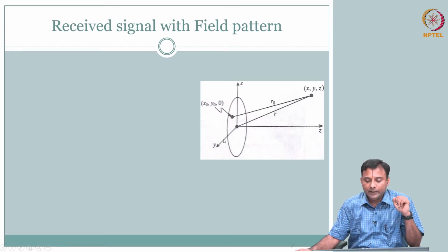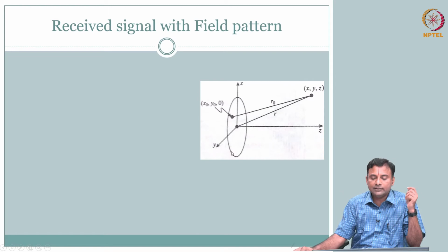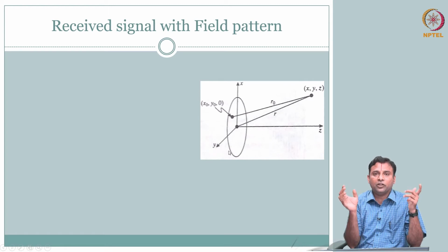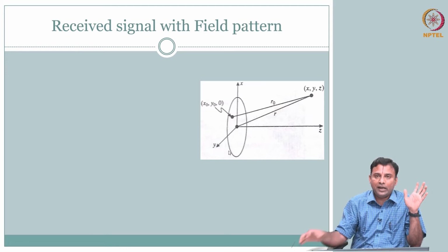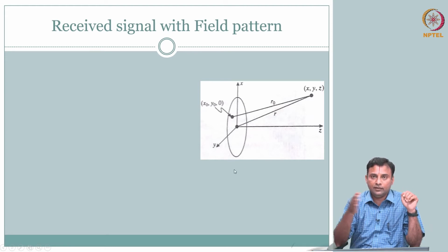Again, for simplicity, there is a circle here, but this can be any shape. Remember, the thickness mode we are not worried about now. The thickness is going to determine your resonant frequency. That part is taken care of. So, pretend you have some thickness, so there is some fundamental resonant frequency. Now, we are interested in the shape and size of this transducer crystal.